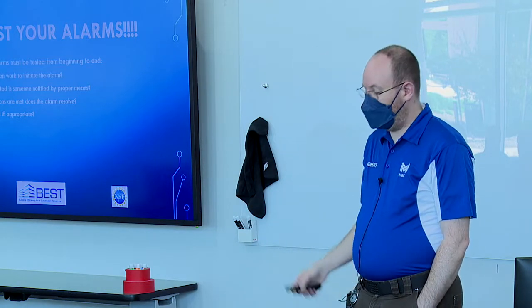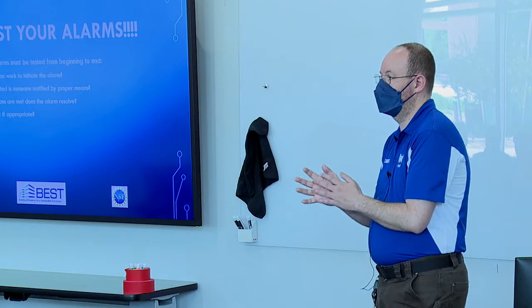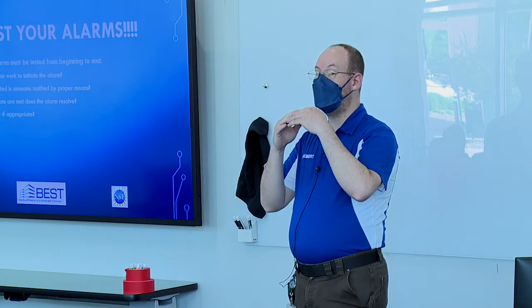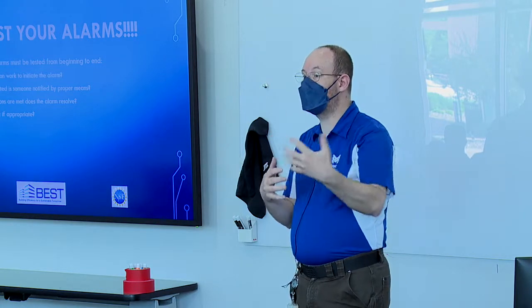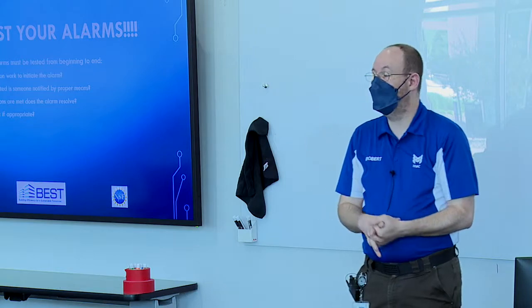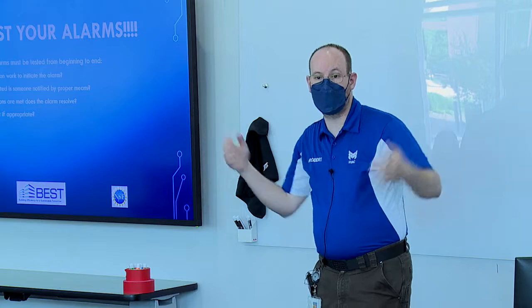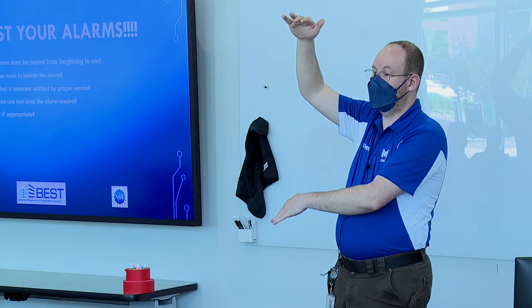Okay? And sometimes that is an onerous task. Depending on your control system, sometimes you have to go in and manually set up every stinking alarm. Okay? Also consider when you're doing those messages, is there a temperature reading or an associated data point that is useful to include in the data for that alarm? Room temperature out of range, room 117 at 82 degrees. Okay? Am I dealing with over range or under range? Those types of questions. Okay?